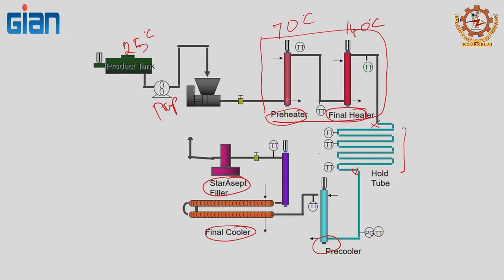This is a more traditional tubular heat exchanger or scraped surface heat exchanger. In the case of microwave, you may be using a microwave heater. In the case of ohmic heating, you are using an ohmic heater. So, the concept for aseptic processing can be adapted to ohmic or microwave heating, and you are able to achieve the same products.